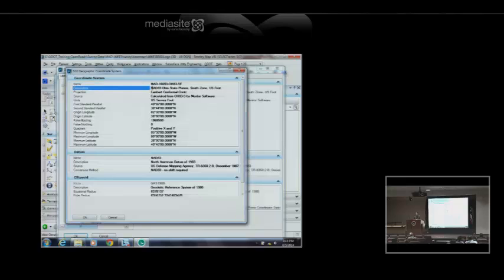And I also am recommending that you put something in here, ground coordinates, to identify this isn't the NAD 83, maybe OH83 South. This is an edited coordinate zone. So given it a new name, and I've told it in the description, this is ground coordinates based off of that NAD 83.